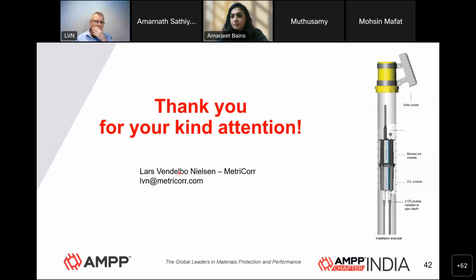Yeah, well, maybe the question would be rephrased. Is there some kind of range of the cathodic protection potential that we should be within if we are safe also regarding AC corrosion? If that's the question, it's really something that depends from soil type to soil type, and also depends very much on the resistivity of the soil.